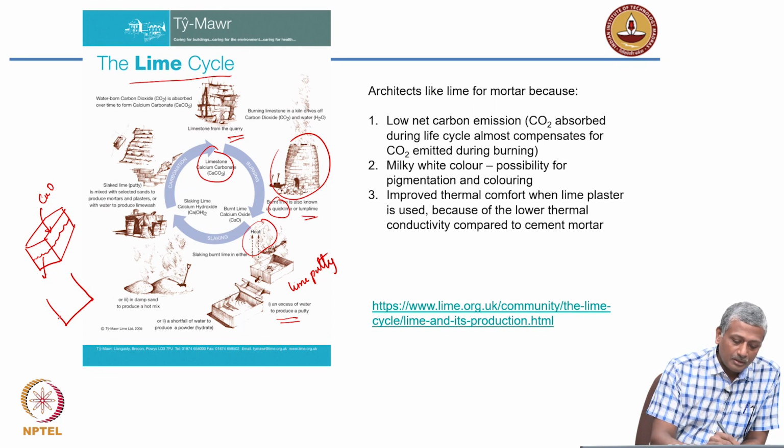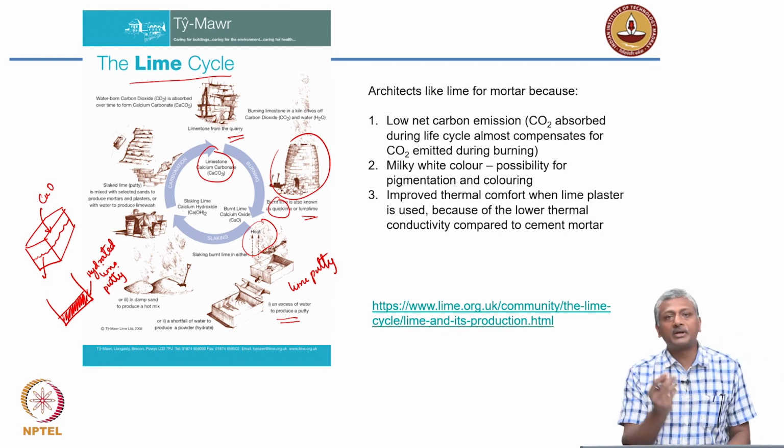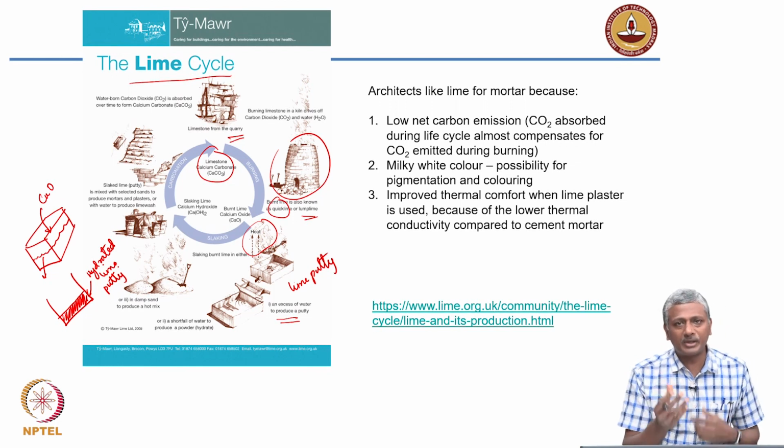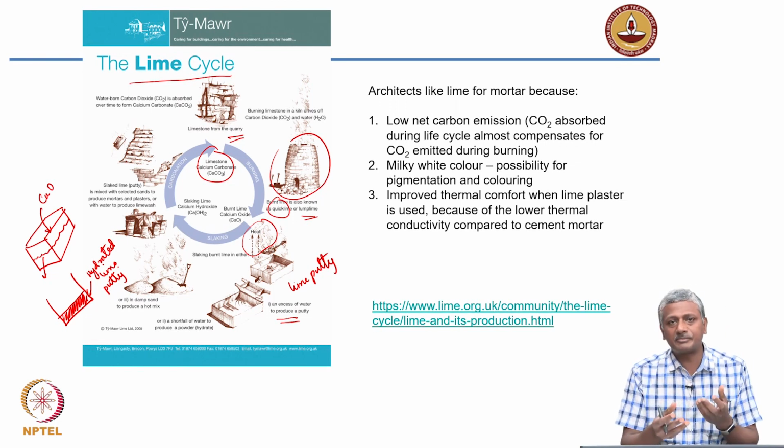The bottommost part forms a nice plastic hydrated lime. All the lime gets hydrated ultimately, but what is in the bottom is called lime putty. Lime putty has a nice plastic nature about it, and you can mix it nicely with sand, sometimes add some extra water to make your lime mortar.